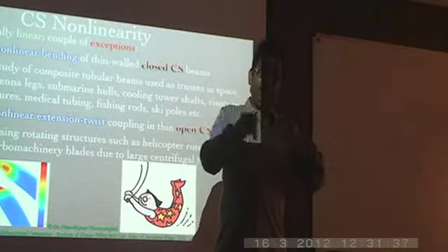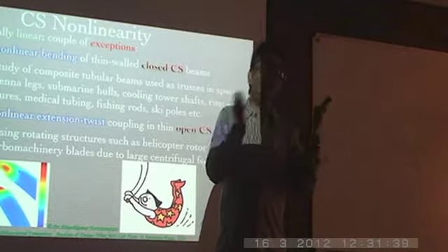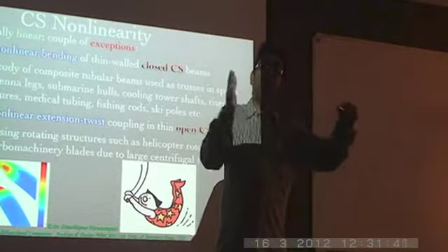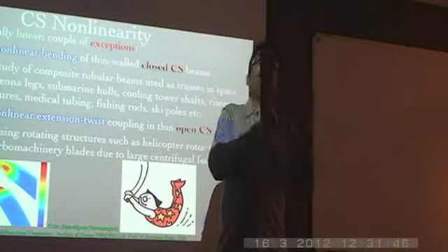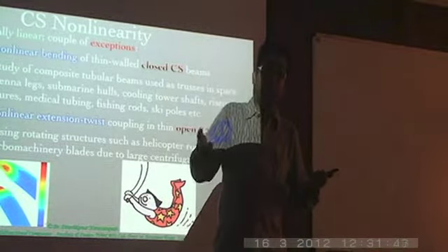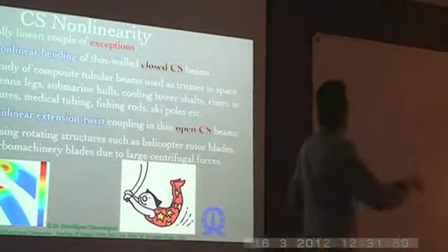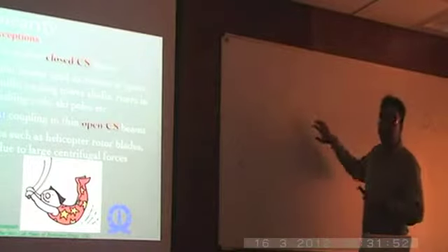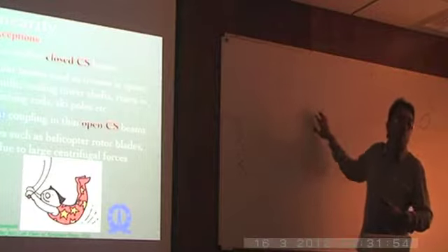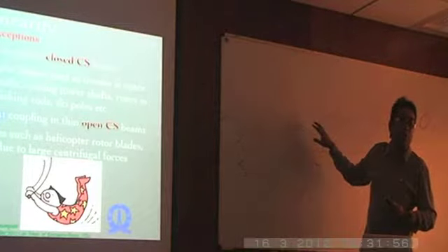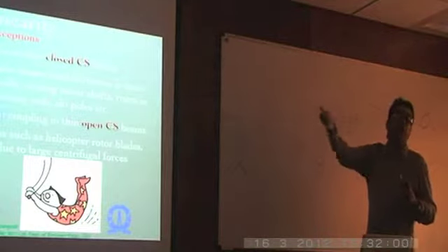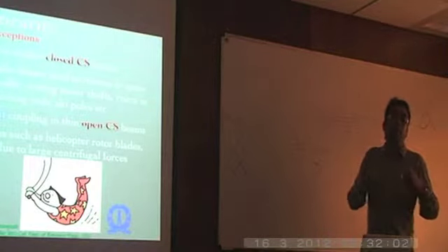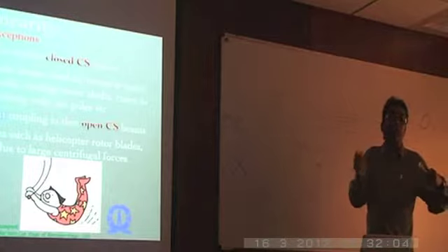Whereas it is because of a geometric feature, that because of asymmetry, for example, you can have the shear center and the centroid separate from each other, and that can cause a different type of coupling. So most of that will be observed in having non-zero values for your off-diagonal elements over here. In particular, let's say the transverse shear and the bending will be coupled, the extension and the torsion will be coupled.